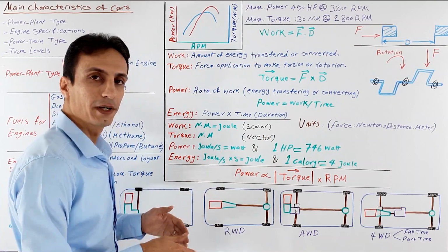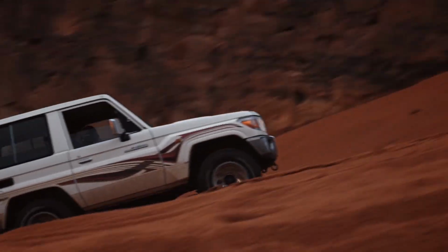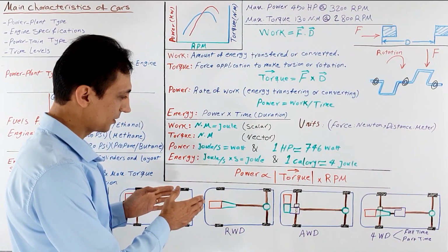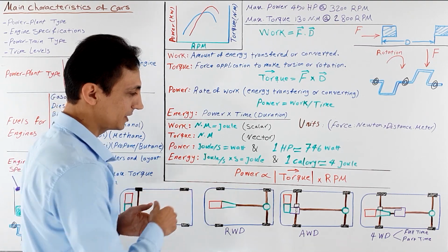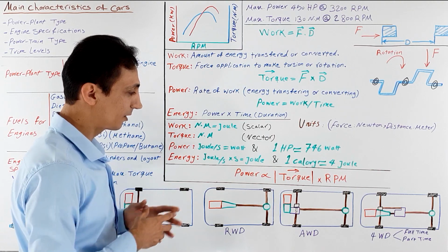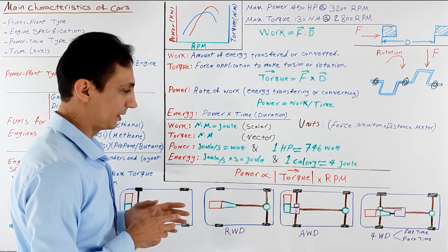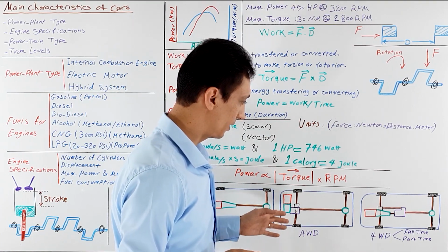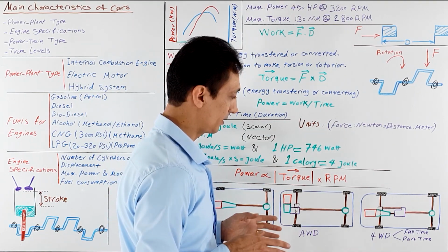Shifting the weight to the rear wheels in uphill driving conditions makes this powertrain design desirable in many cases. But the space that is occupied by transmission and propeller shaft is a challenge for designers, and also unbalanced rotation and vibration can bother occupants.